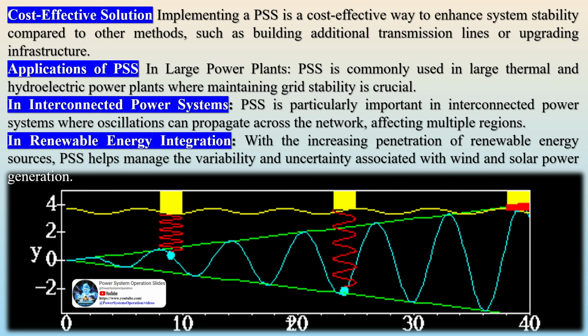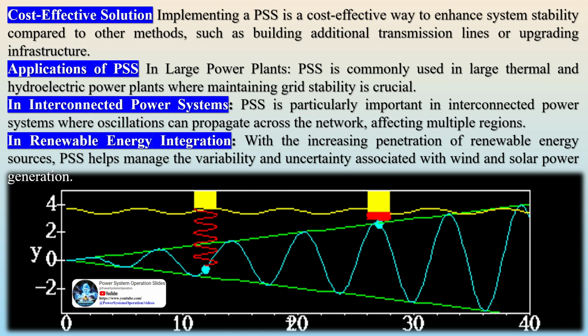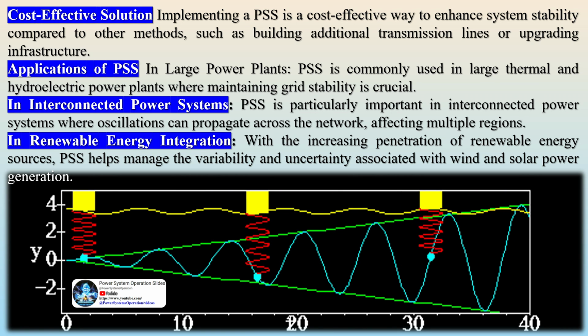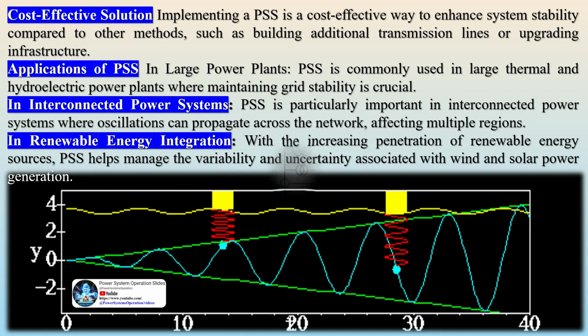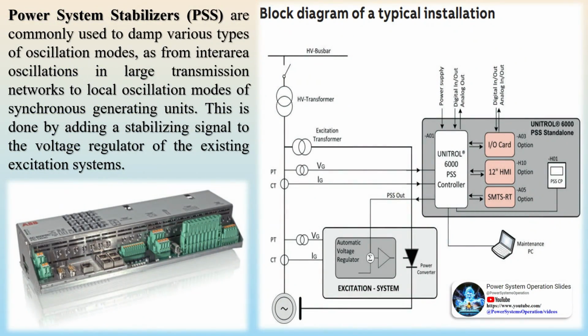The PSS contributes to the reliable operation of the power system, ensuring that generators remain synchronized and that voltage levels are maintained within acceptable limits. Implementing a PSS is a cost-effective way to enhance system stability compared to other methods, such as building additional transmission lines or upgrading infrastructure.